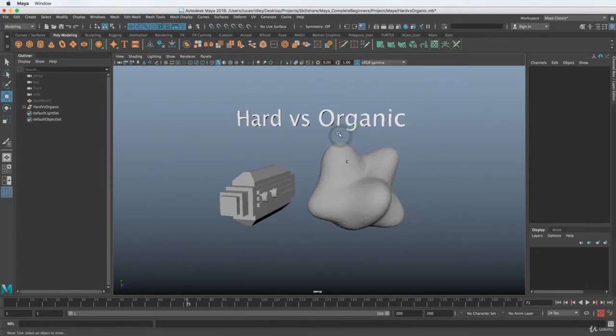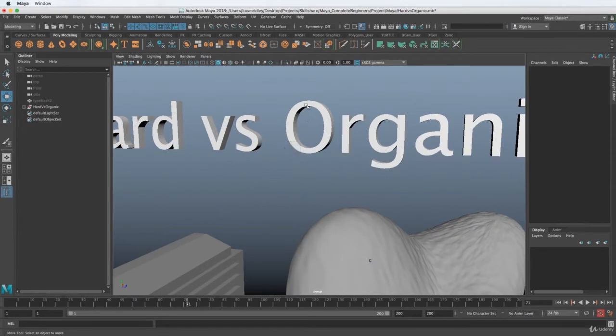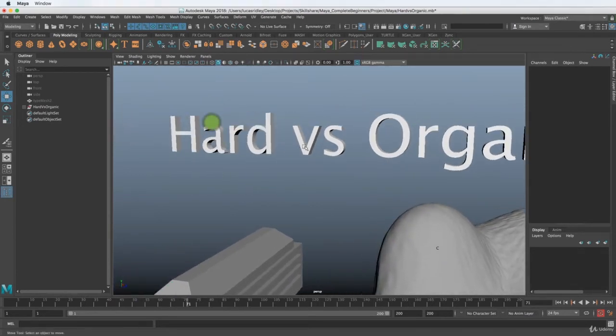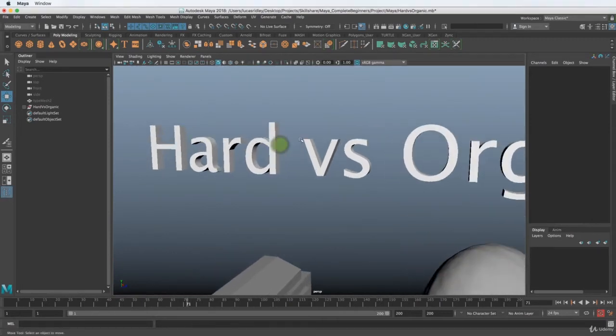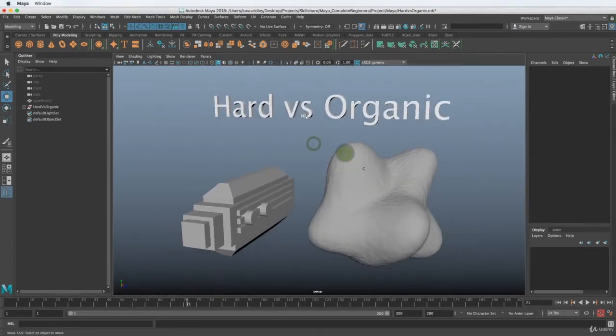Let me first quickly cover a couple of little tricks that I like to use in the Maya viewport so we can look at this a little better. I don't know if it shows up in your video, but the edges of all of these polygons are not super smooth. They're jagged and not anti-aliased, as we say technically. There's an anti-alias button here that you can turn on for the viewport, and it is this little one right here.